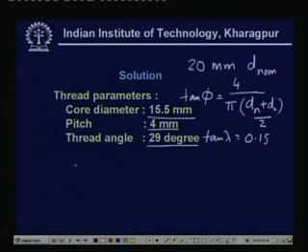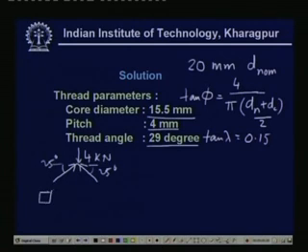Then from this given data, we will have to calculate the force on the knot. So, that is again done by elementary static analysis. If you consider 4 kilonewton here, then of course, you get this was 25 degree and again this is 25 degree. So, we have to calculate the force over here, then this force is again transferred to this knot again from this side, and we have to calculate the net force.